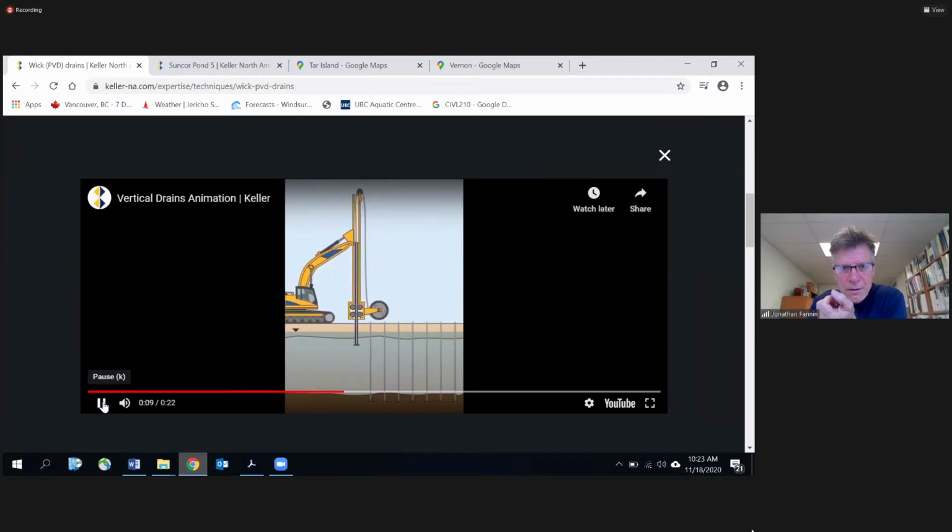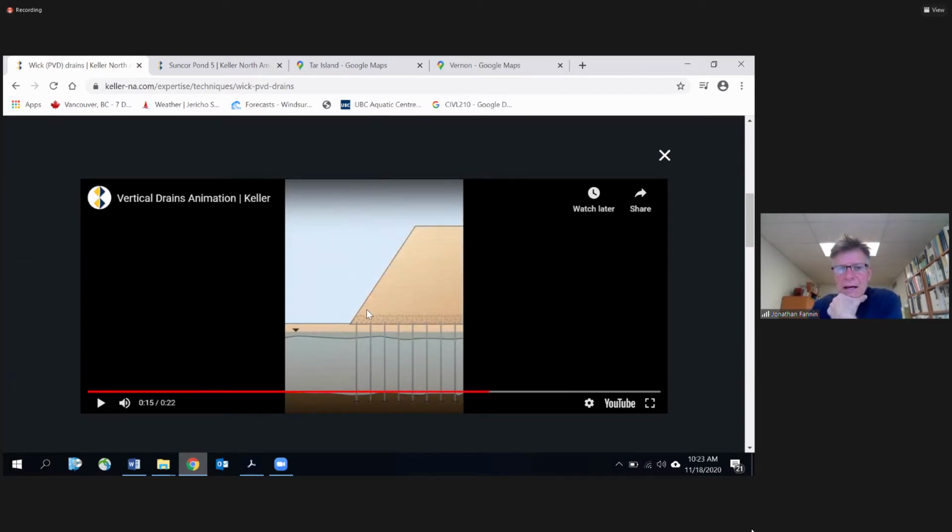Let's see another one. And I'll try and stop it. Oh, there we go. And you capture it, you wrap it around a little steel plate here. It's like an arrowhead by the time it's finished, I guess. But you drive the mandrel down, you wrap this tiny flexible steel plate over the end of the drain, and it gets pushed down, and then when you withdraw the mandrel, it just acts as a fish hook to hold it at the base. You pull up the mandrel and then cut it at the ground surface and do the next one.